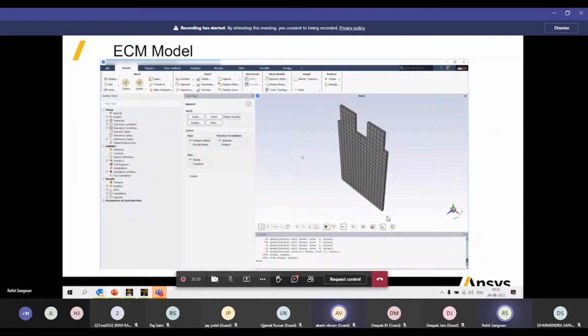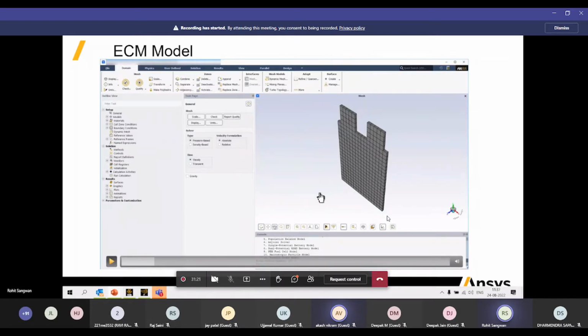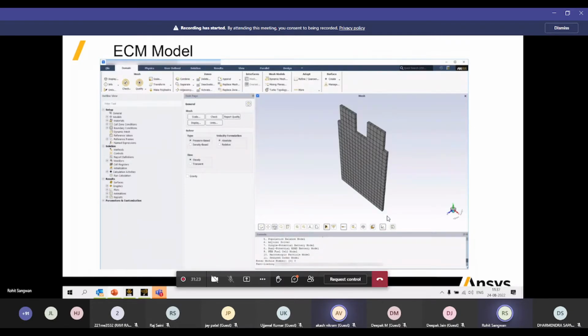To start, I'll load an MSMD battery add-on using the text command interface. I'll enter 8 to load the dual potential MSMD. So this is the older version where we had the battery module, which was started using a text command in the console window. Now we have a direct option to turn on the MSMD battery model.